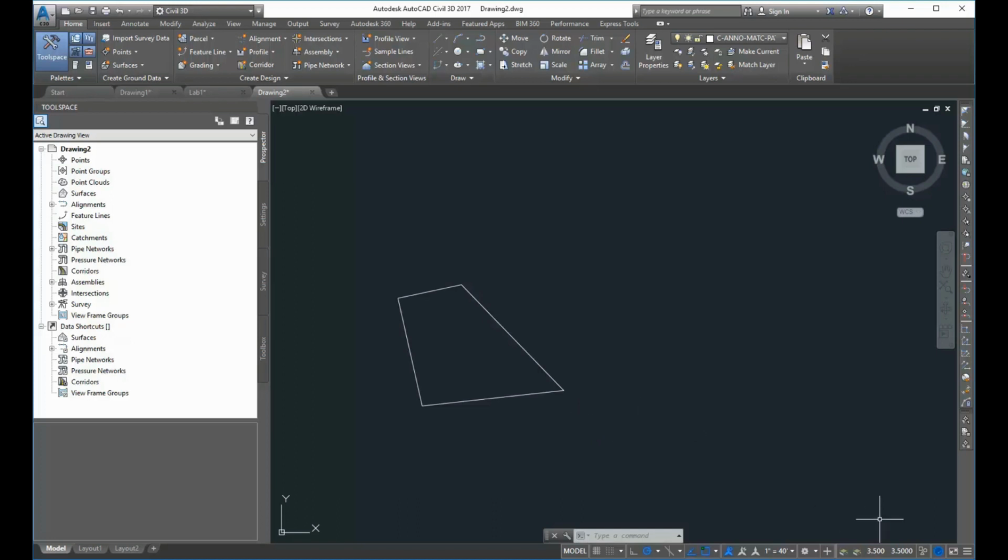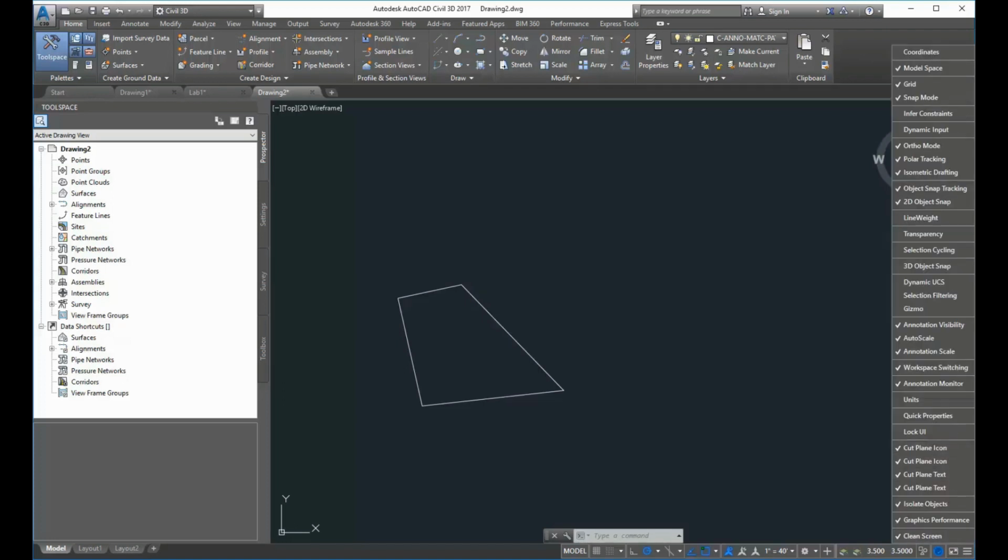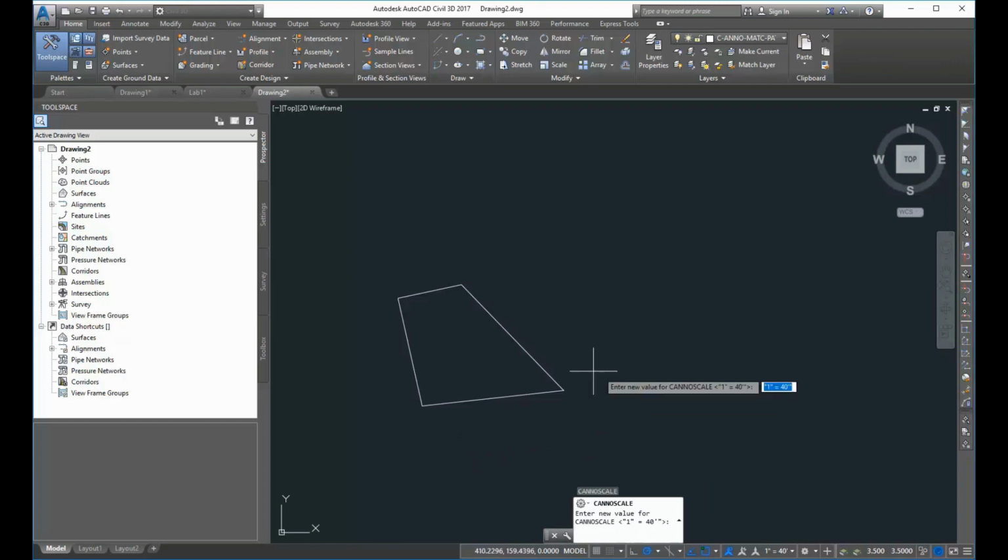So if you're going to be concerned about coordinates or using some of the features that require inputting of coordinates, down here in the lower right-hand side, you can change what is showing up on your bottom menu. So far we've really only used this OSNAP command, but I can turn on coordinates, and now I can see as I move around, I have no Z coordinates.